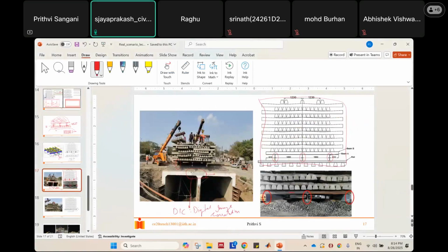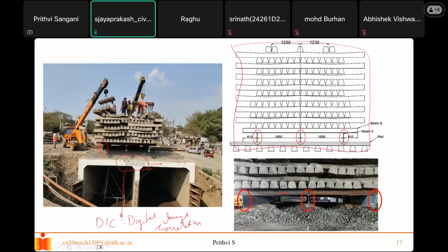Here the culvert, when you are testing, was not in use, right? Yes, it was not in use. We have lateral earth on only one side; the other side it was not there. Even that was taken into the calculation for these maximum displacements. The lateral earth was there on one side and not on the other side. That was considered. So it was like a model box girder.